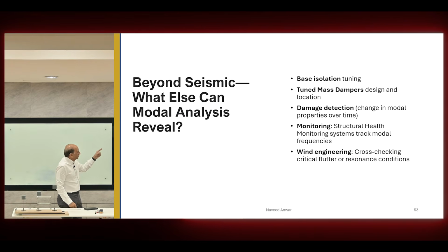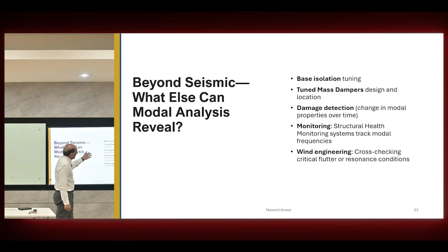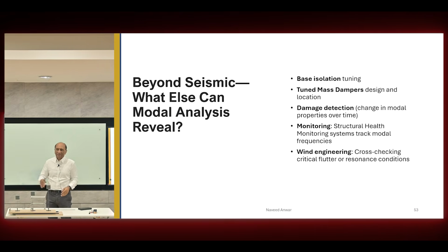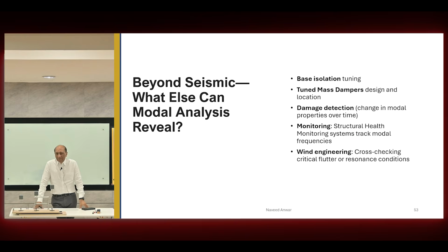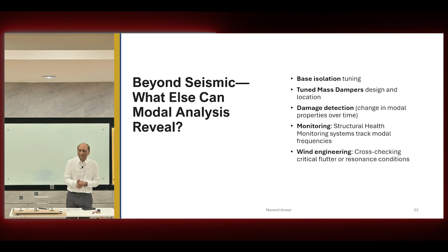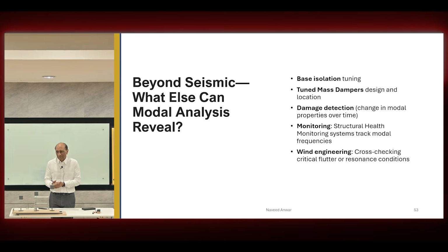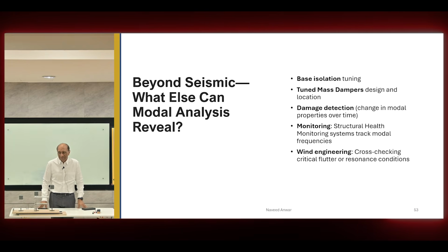The modal analysis can also be used for many other things. For example, design of the mass, base isolation, tuned mass dampers, damage detection, monitoring, wind engineering. Everything depends on modal analysis. Without that, there's nothing you can do, especially advanced systems, all depend. Like I said, you're young people, you don't go to the hospital. Every time we go, the first thing is they say, go check your pulse before I send you to any doctor. It doesn't matter what your weakness or problem is, the first thing is heart rate, right? Same thing. Any analysis you want to do with the building, the first information is to look at the modal results before you go to any specialist.